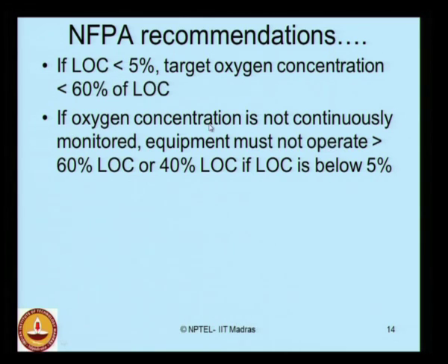If oxygen concentration is not continuously monitored in your plant, the equipment must not operate above 60% of LOC, or 40% of LOC if LOC is below 5%. These are NFPA recommendations for avoiding fire accidents or explosions under combustion.